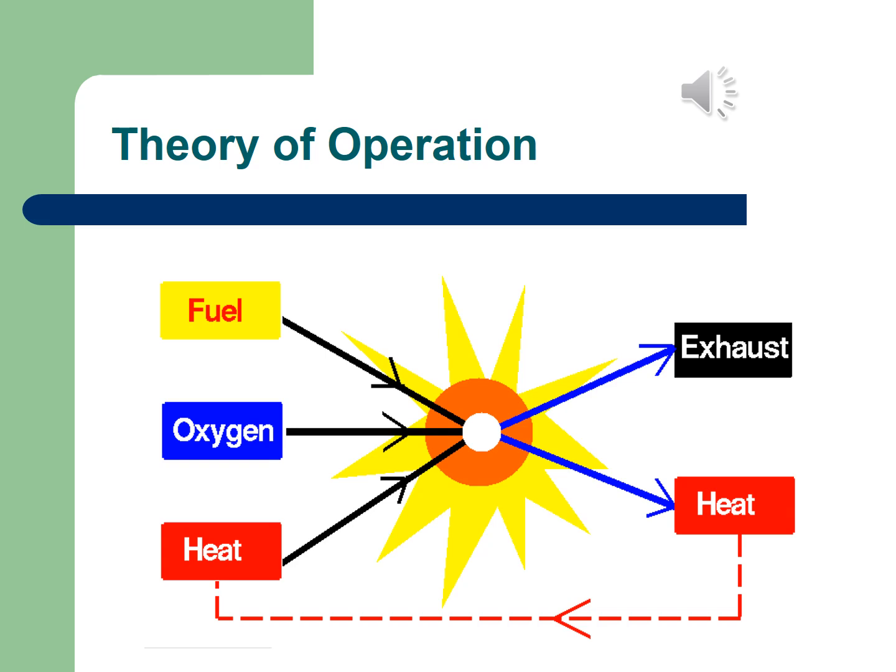Otherwise, we can have wastage on both ends, because oxygen can cool down the furnace if there's too much oxygen, and fuel can be wasted again if there's not enough oxygen, and it can also be dangerous eventually. One thing that you can see in this specific diagram is that you will also have your heat.